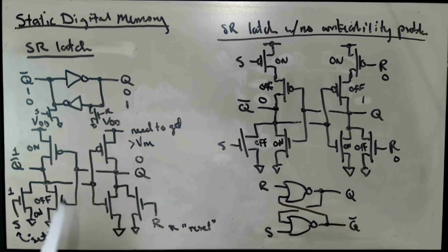However, this comes at the cost of having two extra transistors. And sometimes when you're building these kinds of memory elements, for instance in the context of a static RAM, where you want to have as many of these circuits that could store a bit of information packed in a given area as possible, having those extra two transistors in there is something you don't necessarily want to do. And so you wind up putting up with having to size these transistors appropriately, and worrying about that writability problem for the sake of getting the density up.